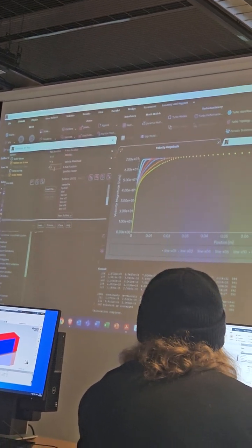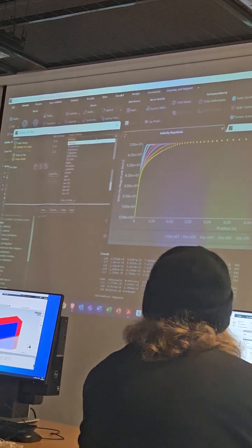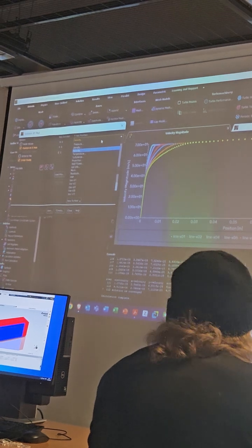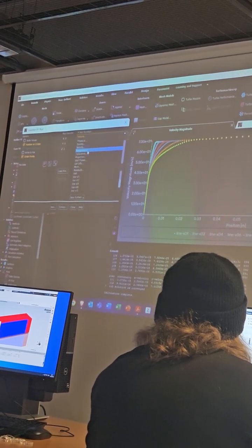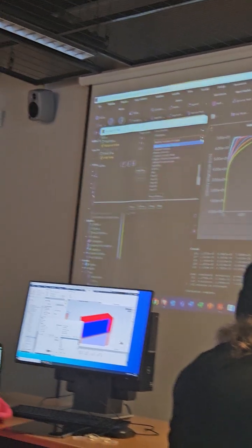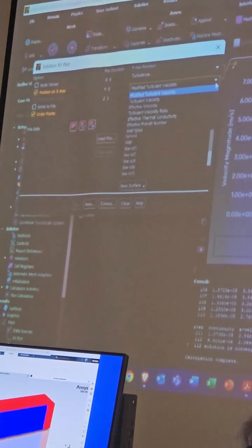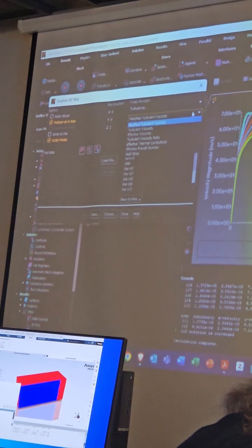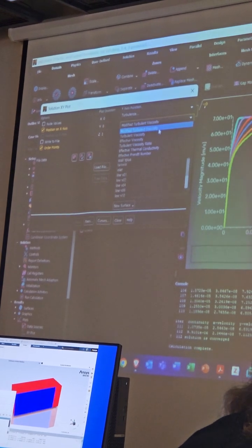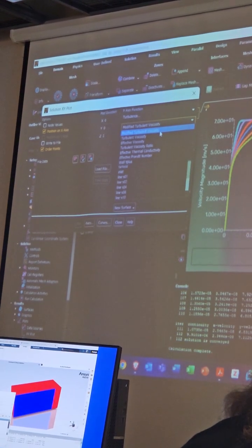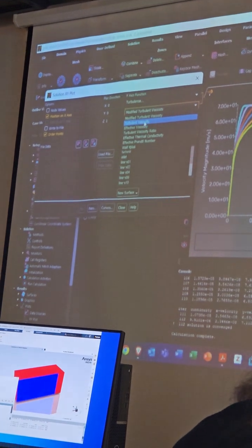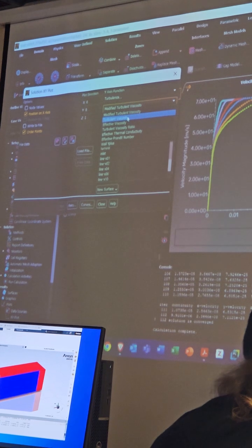Z direction is correct. In the y-axis function, we need to find the additive viscosity. So instead of velocity, we select turbulence. And in turbulence, in the second box, there is modified turbulent viscosity. This is the variable that Fluent is calculating for the Spalart-Allmaras, so that nu tilde. That's not what we want. We want the additive viscosity, that is the turbulent viscosity, so the second variable.